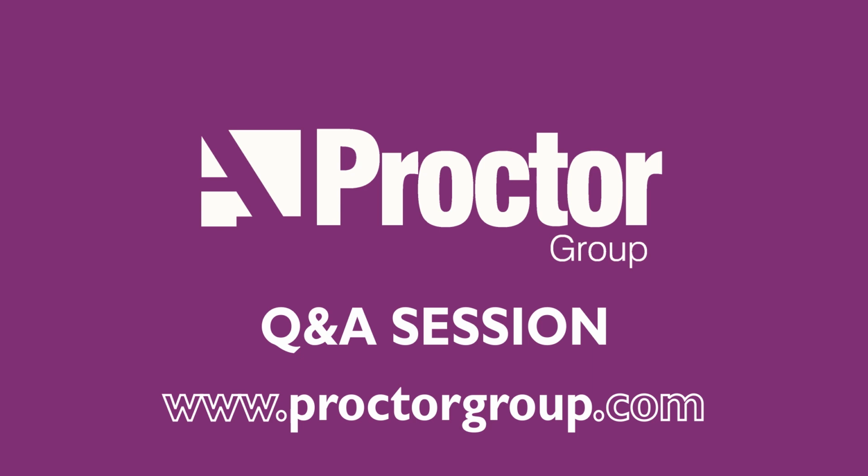For me, certainly, WUFI analysis looks further at the location of where the modules may be finished and positioned within the country. So we find that WUFI looks at localised areas rather than the UK in general. Furthermore, depending on when the modular is completed or how far it is completed, i.e. is the external skin on, or is that being completed on site, it can then look at temporary moisture within products during that movement or during the application still being done on site.